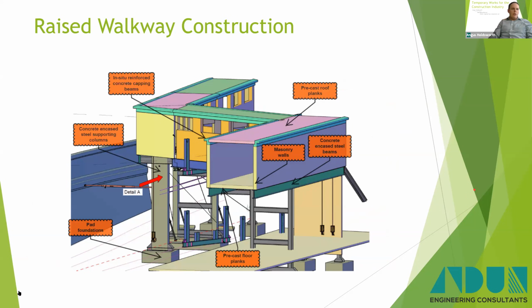So we decided that the best thing we could do, given the constraints and the time we had available, was to cut it and lift it out in pieces. So the first problem you've got is, where do we put the crane? The only possible position for the crane was in the adjacent road, and it was very, very tight.